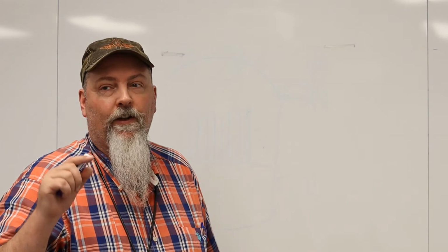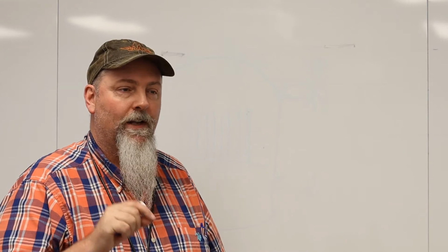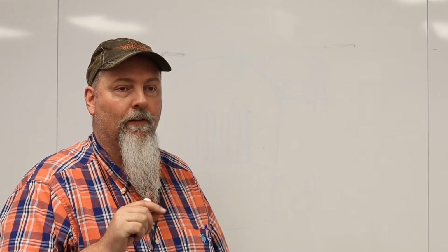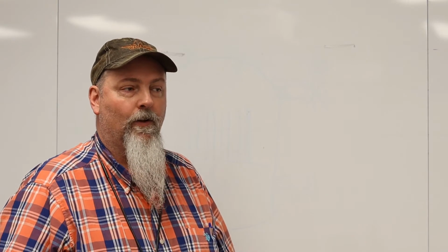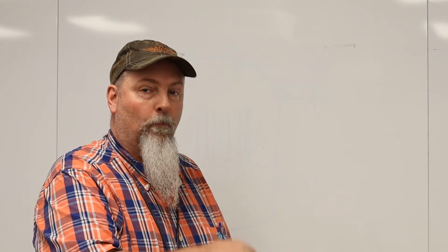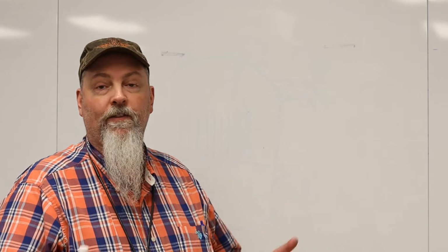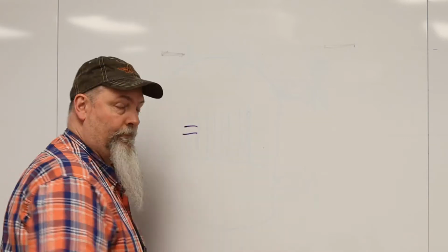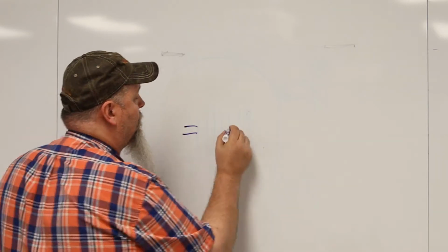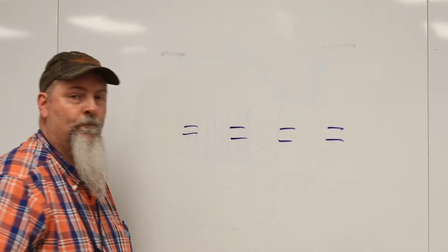And I see in the discussion posts already, some of you are getting a little confused on what the logic means. Because we're looking for a valid signal, we want to use redundant instruments, redundant sensors. So I'm going to draw these sensors as contacts, like that.